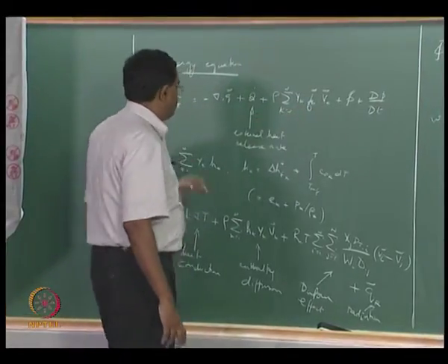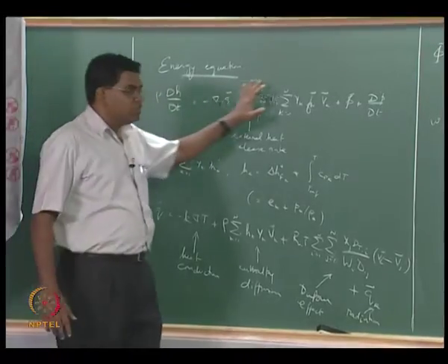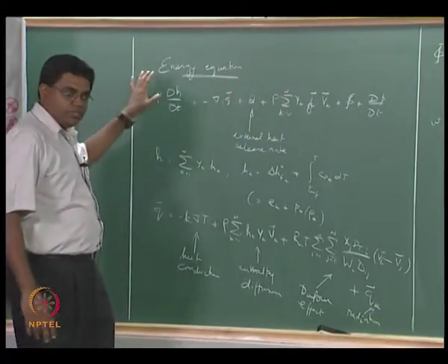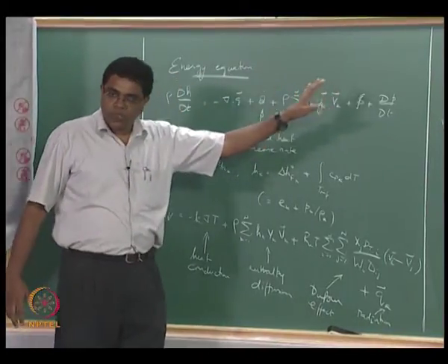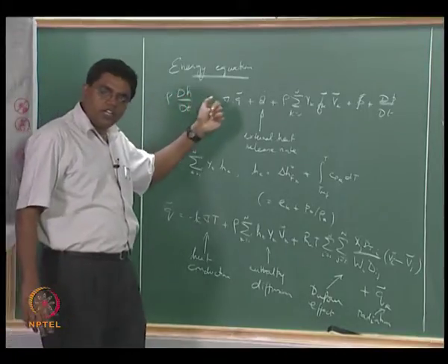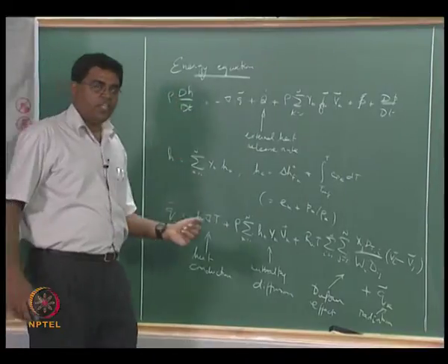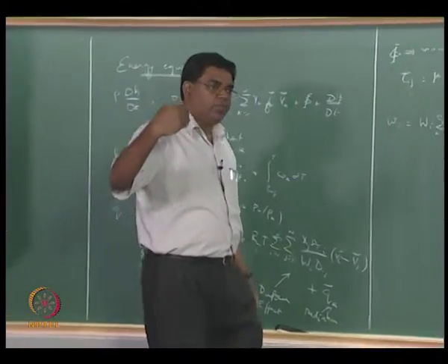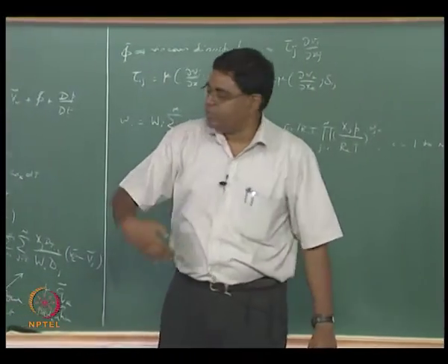This is coming from the fact that, recall, this equation is a thermal energy equation. You could write out the total energy equation by writing an equation for conserving the stagnation enthalpy, right. The stagnation enthalpy would have the static enthalpy plus the velocity squared by 2, right.